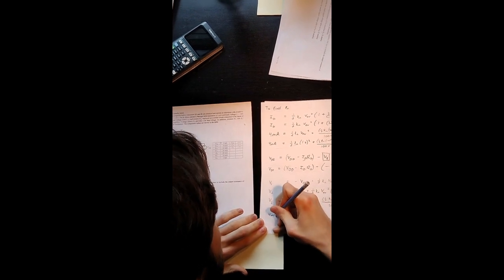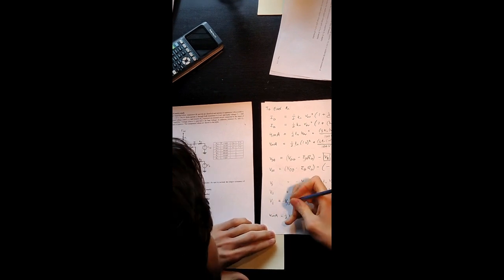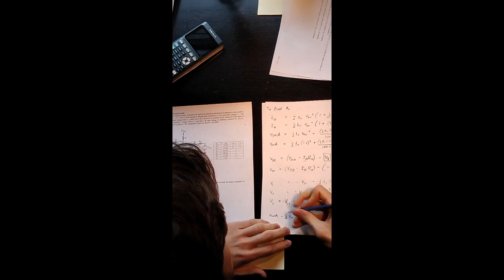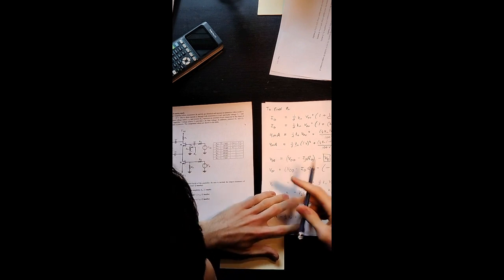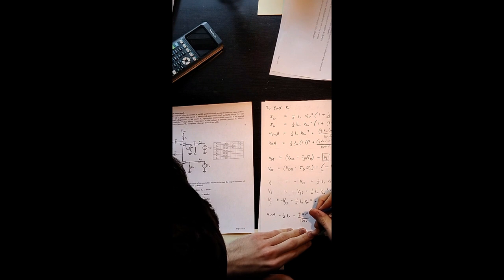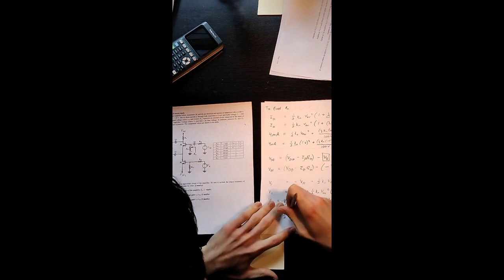Okay, so if we were to bring this down, we would get 4 milliamps minus 1/2 KN times 1 volt squared, so that's easy, plus 1/4 KN squared over 100 volts times VDD, which is 5 volts, and that should be subtracted.